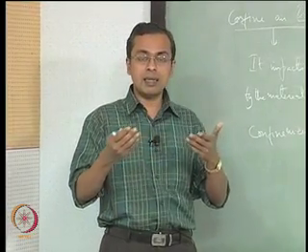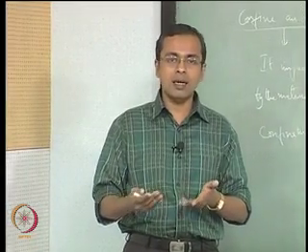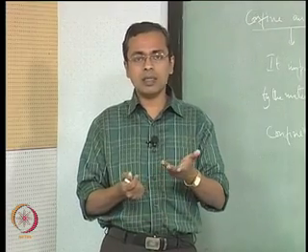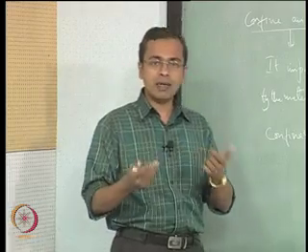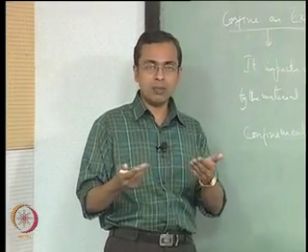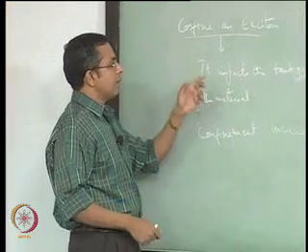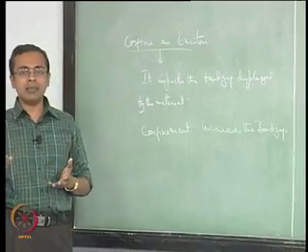But there are many places in the electronic devices field where you end up having to use a dissimilar material contact, because the band gaps that you are looking for and other such details may be different for different materials, and therefore you may need that combination to make it work. So now by doing this confinement for the same material you can change the band gap.